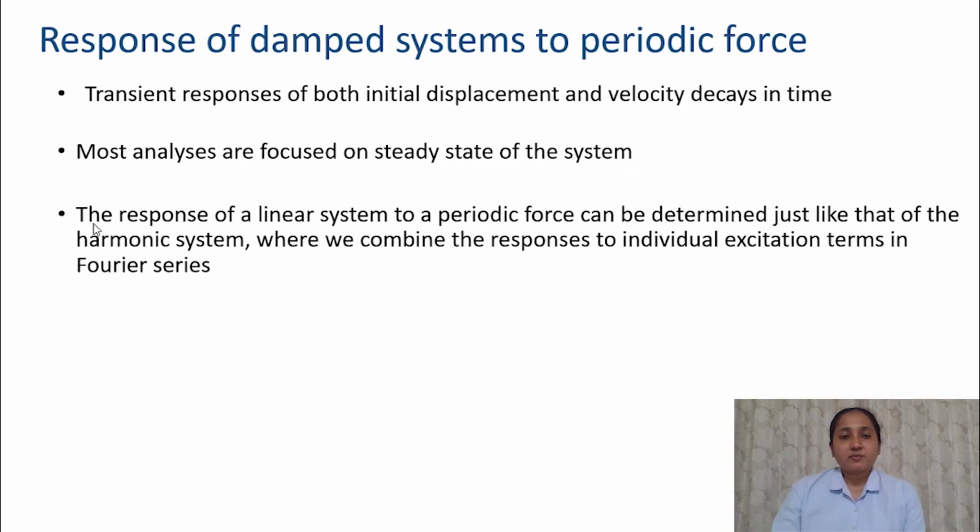Now, the response of a linear system to a periodic force can be determined just like that of a harmonic system. Here we combine the responses to individual excitation terms in the Fourier series. We just have seen that a periodic function can be separated into different harmonics using Fourier series.